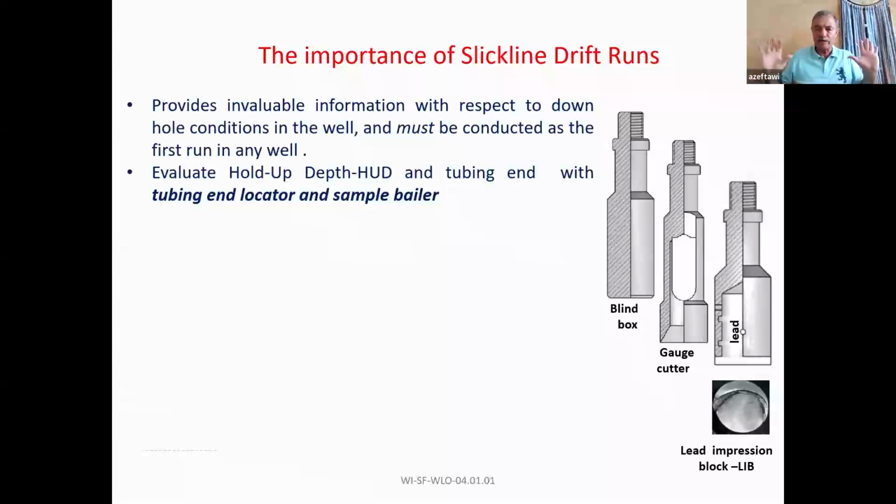It's like a check valve, one way. So you have to check that the formation is permeable enough to accept this. That's why we do the injectivity test. Once we did the injectivity test, we started bullheading. Bullheading is squeezing the kill fluid and whatever is inside the tubing back to the formation. This is the killing. And normally the well will die between a tubing volume and double a tubing volume. Yes, we have some wells that will die after pumping 10 times the tubing volume. But this is not the standard yet.